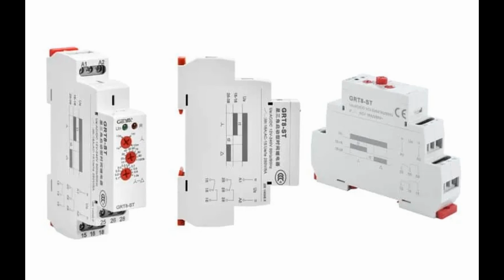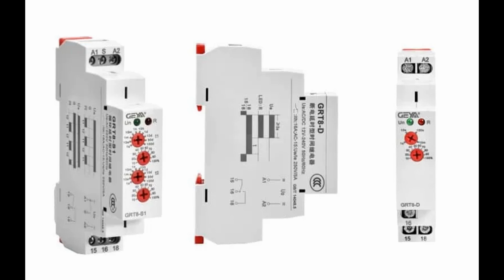Interval delay. Interval delay relays provide a delay between the activation and deactivation of the load, with the relay contacts toggling between two states at regular intervals. Once the control input triggers the relay, there is a delay before the contacts switch to the energized state, e.g., closed, activating the load. After a predetermined interval, the contacts revert to their initial state, e.g., open, deactivating the load.